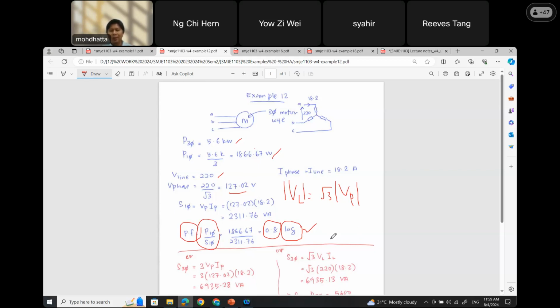Except for one topology of electric motor, which is known as the synchronous motor, where the power factor being supplied goes back and forth. If we have the synchronous motor, it would be a negative value of reactive power, so our power factor later on will become a lead power factor. That's another case.